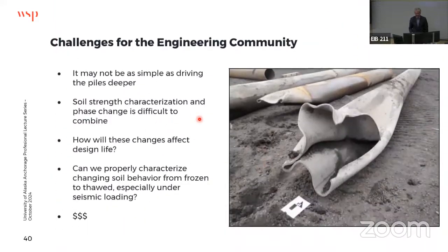And the challenges to us, I gave you the example of the Kivalina Bridge and driving piles. It may not be as simple as just driving the piles deeper, right? This was another project, not Kivalina, where we had challenges driving piles into permafrost. And this permafrost was like 31-degree permafrost, so it wasn't that frozen. And that's what it looks like. So just go ahead and drive a little deeper.